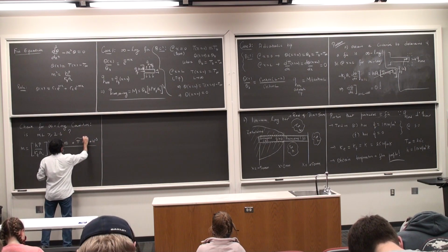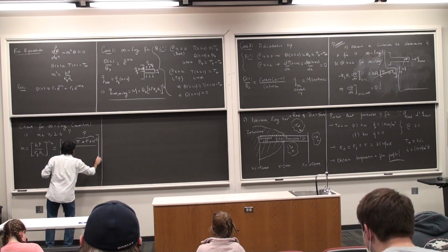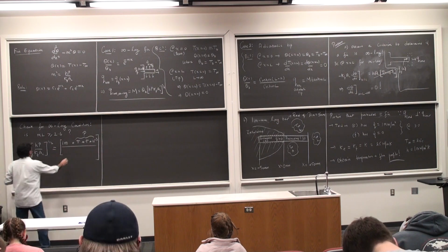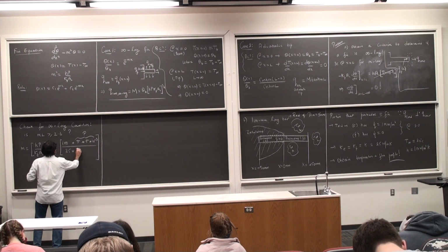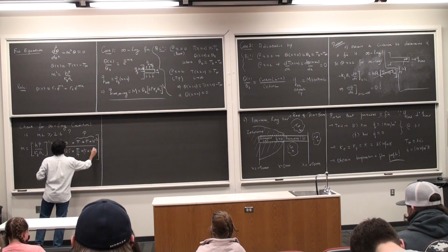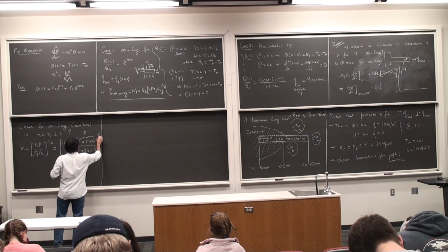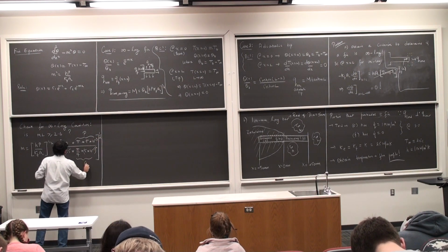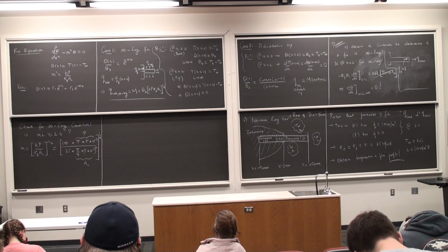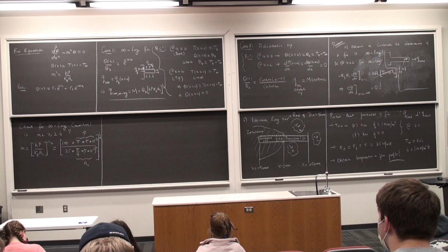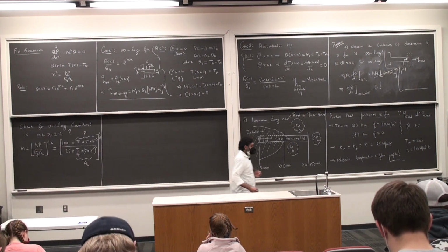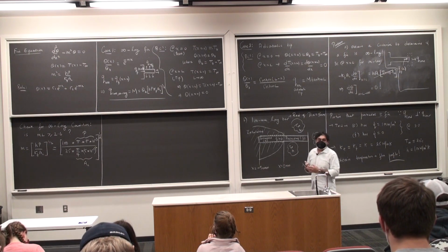Okay, this is the perimeter. Then I have the thermal conductivity of the fin material, which is 25. Area of cross section is a circle. Square, this is to the power 1 by 2. Please do not forget that factor of a half makes a huge difference. If you miss that out, then every fin will become an infinitely long fin, your life will be easier, but you will not be happy after you get your scores. Right? And then we continue calculating this value.